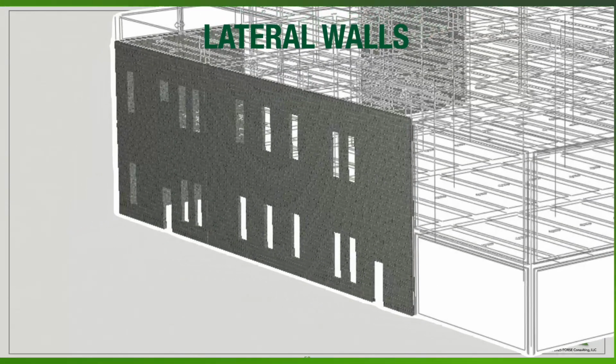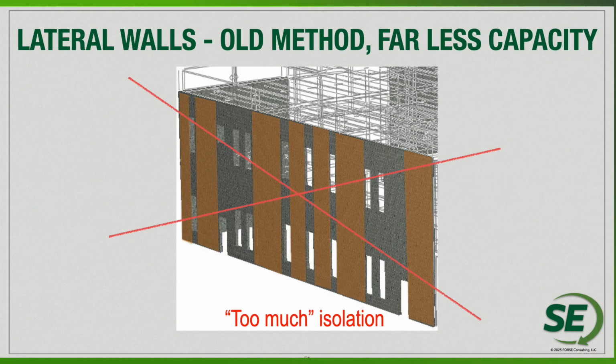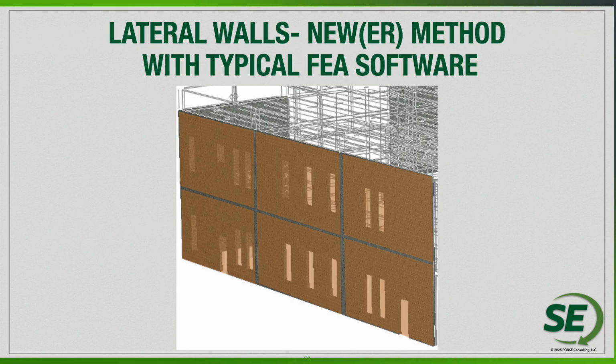So again, looking at an elevation like this, historically, we maybe would have broken the wall down into different continuous wall segments. We have different software tools that even look at walls this way today, but it's certainly going to be diminishing the overall value of what you could use by just having larger panels that are perforated shear walls.